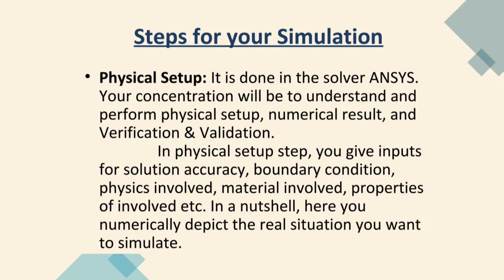Now, then the physical setup. This is another important thing. Fluent already gives some advice on which type of model, like natural convection, what kind of solver you need to use, and what kind of discretization you need to use. So, they already give some idea, or you can do it by yourself with different testing. But remember, in CFD, good results depend on your experience. So, do it again and again, and you will gain experience. What is the problem? Where is the problem? Then you can identify it by yourself.